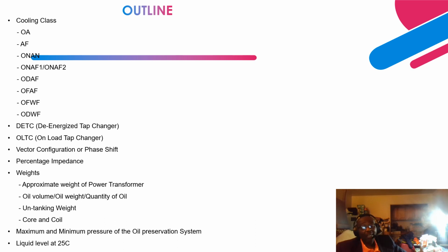If an external contaminant, let's say oxygen, gets into the oil, it is going to degrade the oil and create oxidation inside the oil. So the goal is to create a positive pressure over the oil, and we utilize a nitrogen cushion on the oil. So you have a maximum and a minimum pressure that you need to achieve.